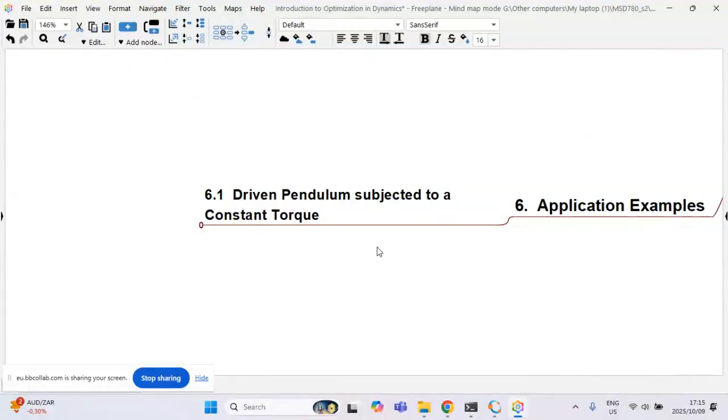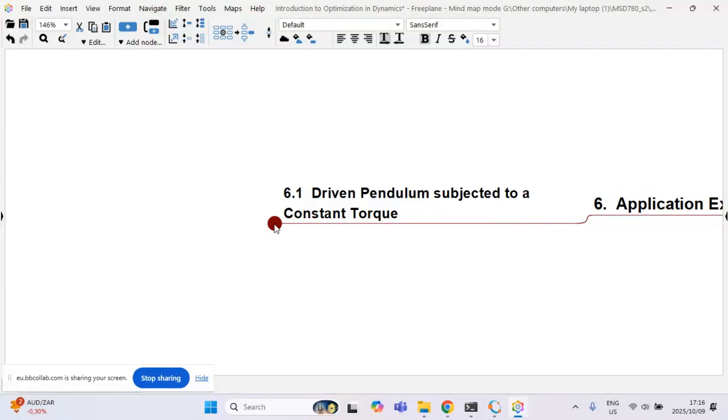Now you'll remember from our previous lectures, this was PR_D that we looked at, where we provide the system with some sort of a constant torque under the enforces.m script. So today we're simply going to take all of those input or model files and start parameterizing them. We're going to look at what parameters we can induce on the system. Is there some sort of an objective function that we can get out, and how will the objective function be influenced by each of these design variables?